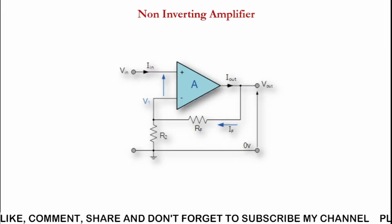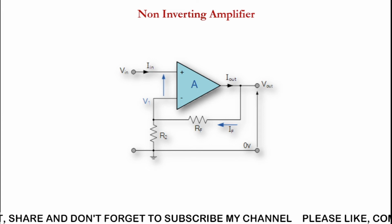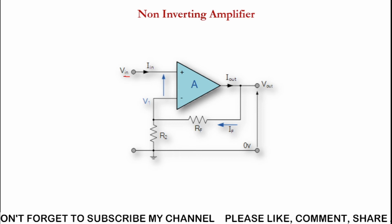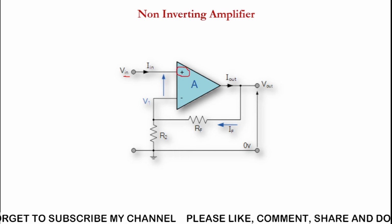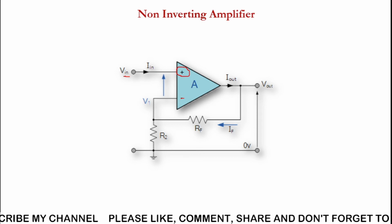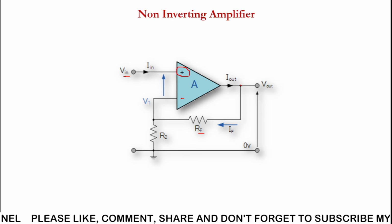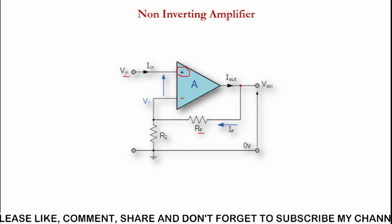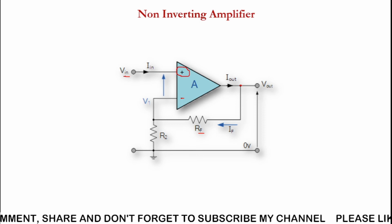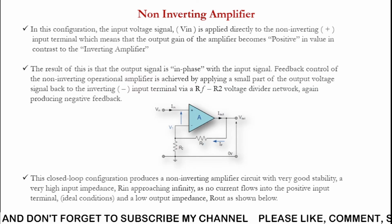Non-inverting amplifier, look here, the input is connected to the non-inverting terminal and the output is connected to the inverting input. So Vin is connected to the non-inverting terminal and the output is connected to the inverting. So for gain stabilization there are no oscillations due to positive feedback. We have a negative feedback only. So look here, there is a feedback resistor Rf that is connected in between V out and V1, and there is a resistance R2 that is connected directly to the ground, called 0.